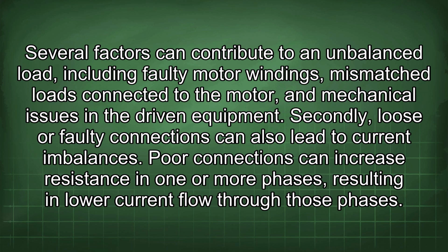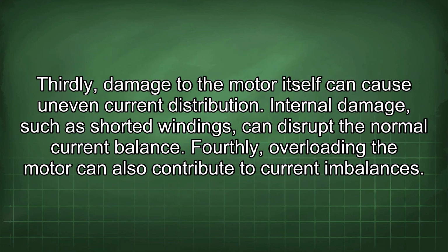Secondly, loose or faulty connections can also lead to current imbalances. Poor connections can increase resistance in one or more phases, resulting in lower current flow through those phases. Thirdly, damage to the motor itself can cause uneven current distribution. Internal damage, such as shorted windings, can disrupt the normal current balance.